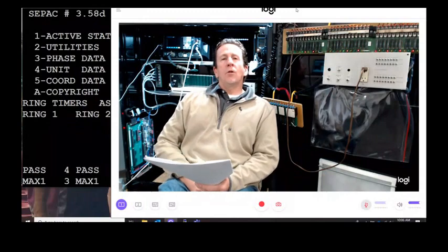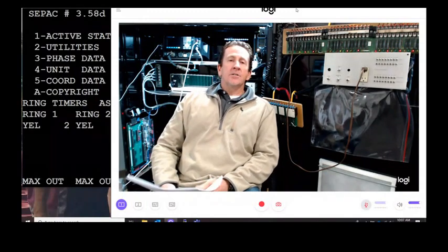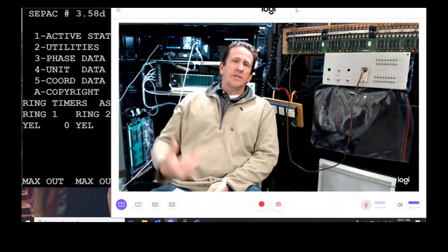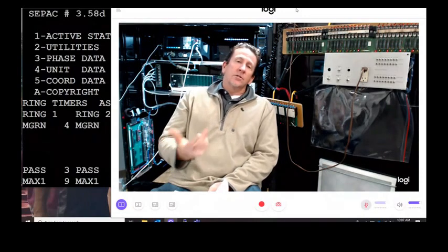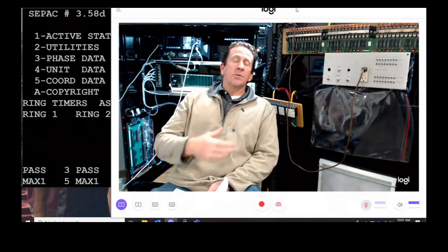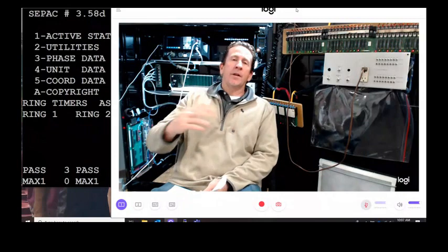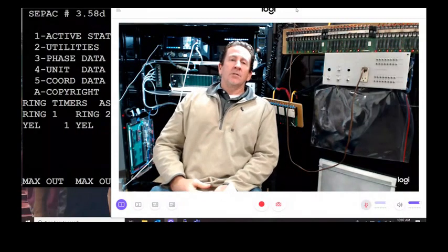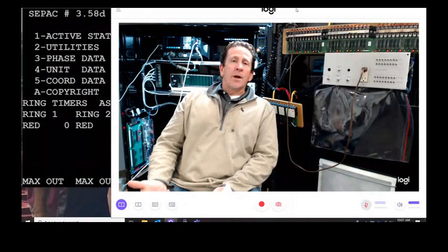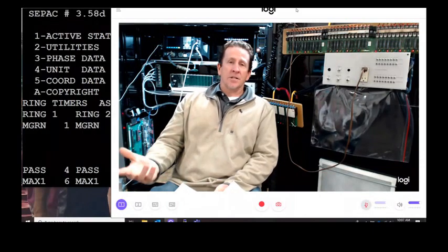We'll have you check all the connections. People always kind of laugh at this. In TS2, as I'm going to show you with the SDLC buses, those connectors, they vibrate, they come off. If it's a replacement cabinet, if somebody was in there before you, they hit something with their elbow and it loosened it up and then it finally popped off. It sounds silly, but what's better than going to an intersection, finding a connector that just came off, plugging it back in, and the intersection takes off and runs?